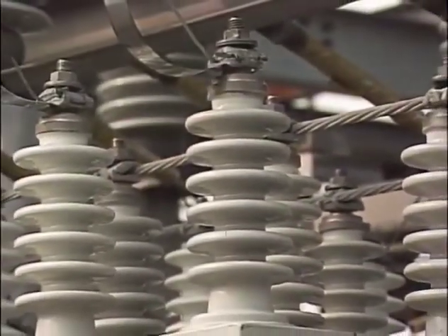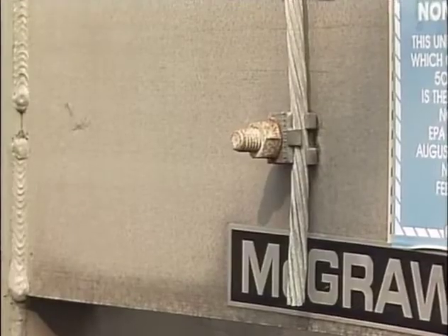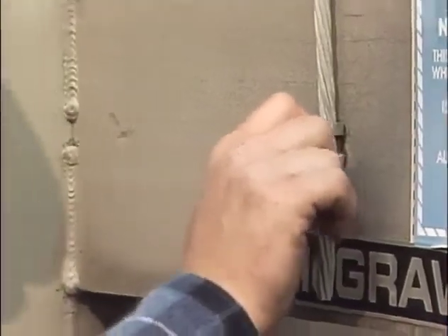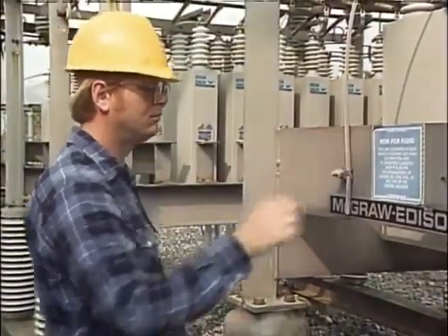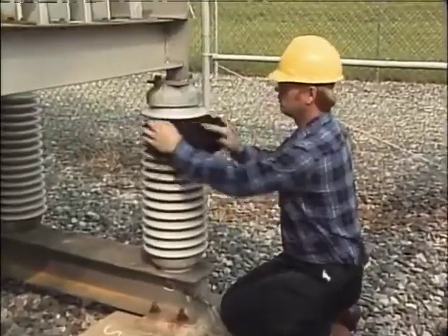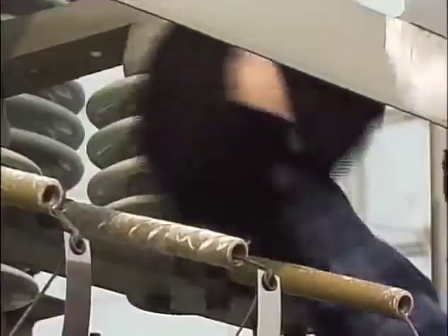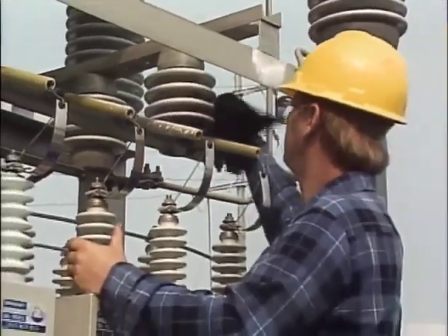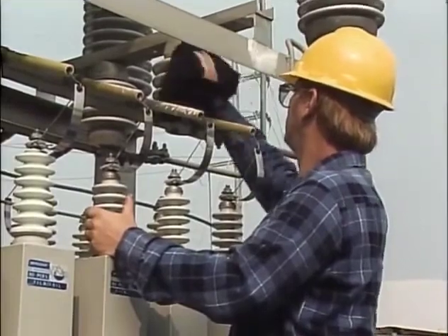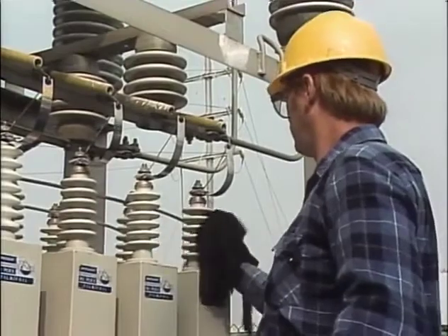These include connections to the capacitor terminals, connections from the source to the bus of the capacitor bank, and connections to the frame of the capacitor bank. Loose connections should be tightened. Corroded connections should be cleaned or replaced. Other items that should be cleaned are all the insulators in the bank, including the frame insulators, bus support insulators, and capacitor bushings. Dirt, greasy film, salt deposits, and other contaminants from the air can accumulate on insulators and reduce their ability to insulate.